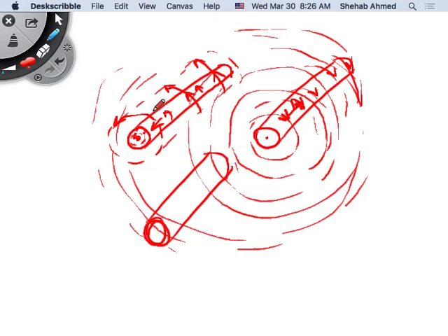Same. So what we want to do is, if each of these are alone, then we know how to treat them, right? But if they're all together in one space, what do we need to do? We need to look at what? Eventually what I would like to do is calculate the inductance of this phase. This is phase A. I want to calculate the inductance of phase A.